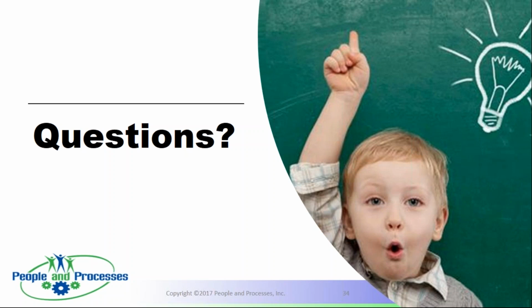As an example, Doc Palmer at Jacksonville Electric Authority talks about when they had 30 technicians at 35% wrench time, and by planning and scheduling work, they changed that from 35 to 55% wrench time. And by the way, when we talk about best in class, it's somewhere in the 55 to 65% wrench time. But when they got to 55%, they realized basically the equivalent of 17 additional people over the 35%, because they were now able to execute much more work. So they saw 17 additional bodies, a total of the equivalent of 47 technicians utilizing that same 30, simply because they were planning and scheduling. They were giving the technicians a head start.